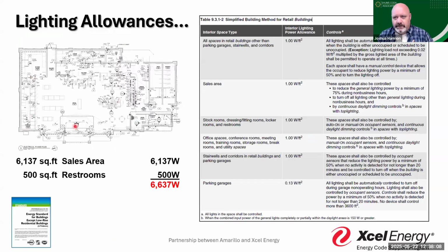When we look at our retail space, for that retail building, see the sales area gets 1 watt per foot. Now, if you remember, the sales area is 6,006 square feet, right? And so I get 6,006 watts.